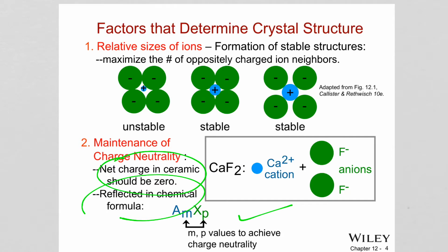So the second thing that is determining the crystal structure, besides charge, was relative sizes, and these are the ionic radii of cations, which you can represent with RC, and the ionic radii of the anions. Because metallic elements give up electrons when ionized, cations are smaller than anions.